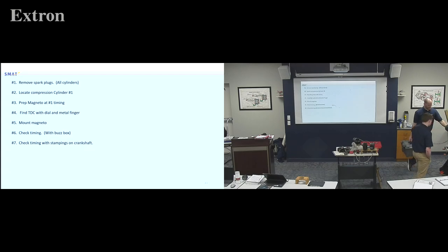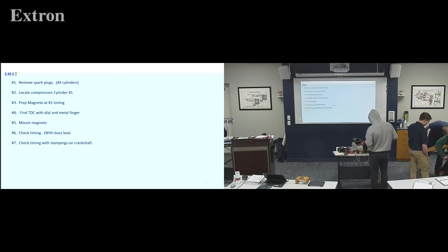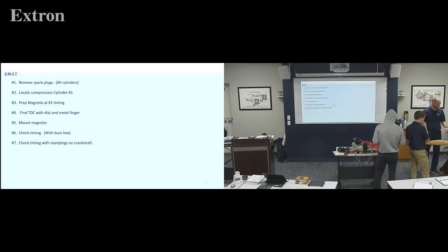Right, and then I would come back, so the manual says you're done. I like a good sanity check. Measure twice, cut once. And I'm looking at 50. Oh, no, that was 42 and a half. Yep. And then the last sanity check is you pull it out and check, am I still in compression stroke? Make sure I didn't somehow get myself turned around in the middle of that.